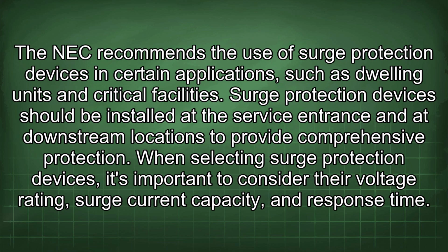The NEC recommends the use of surge protection devices in certain applications, such as dwelling units and critical facilities. Surge protection devices should be installed at the service entrance and at downstream locations to provide comprehensive protection. When selecting surge protection devices, it's important to consider their voltage rating, surge current capacity, and response time.